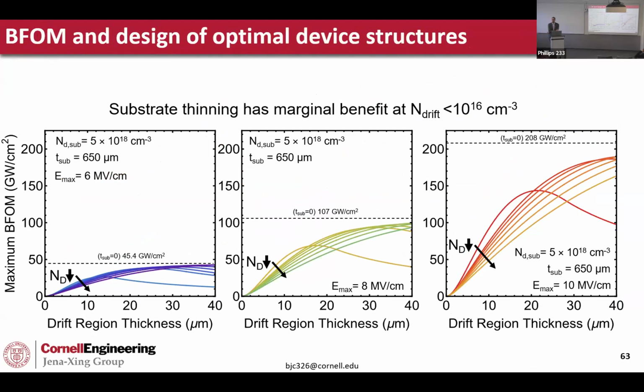I would argue it's an issue, but I'm not sure how big of an issue it is, in the sense that this is an athermal analysis, of course. I've assumed mobility is at the maximum, from 200 down to about 70 as a function of doping. If you increase the temperature, it'll go down, but by how much? If it goes down by a factor of 2, you've increased the resistance by a factor of 2. Is that a big deal?